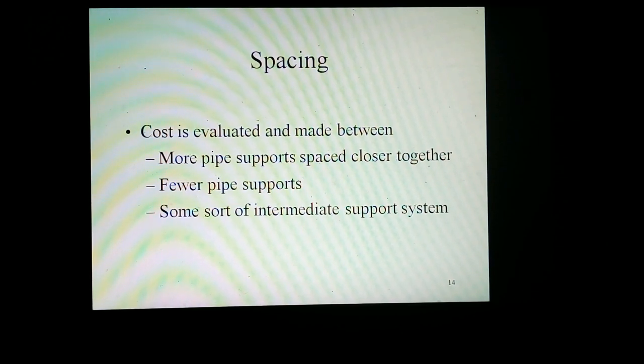Material of construction and fabrication method. What materials are the pipe racks to be made of and what will be the fabrication method? Pipe racks can be bare steel, steel with a concrete encasement or fireproofing, reinforced concrete or a combination. The steel can be steel structural shapes or pipe shape.